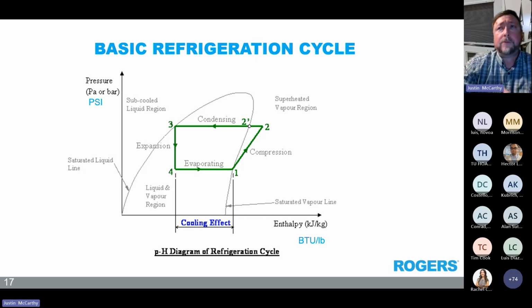In refrigeration, really what we're doing is taking advantage of the changes in pressure caused by condensing and volume, and how that affects the boiling points of that refrigerant. By changing pressure, adding heat, taking away heat, we change the state. And that allows us to move heat around.